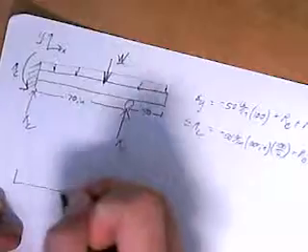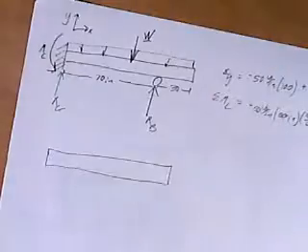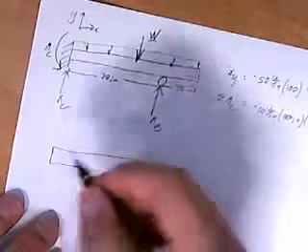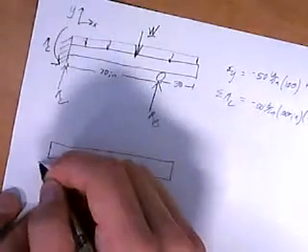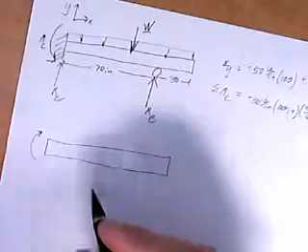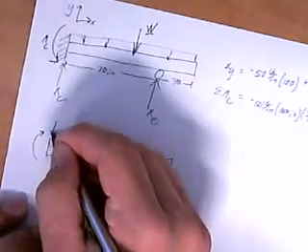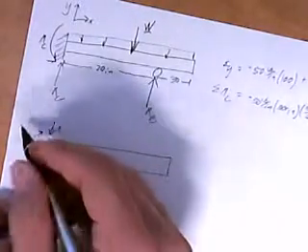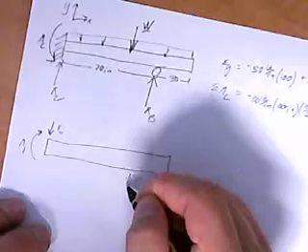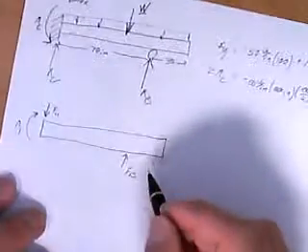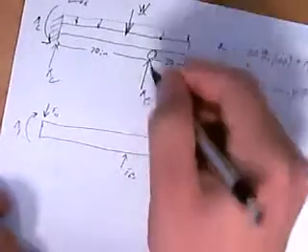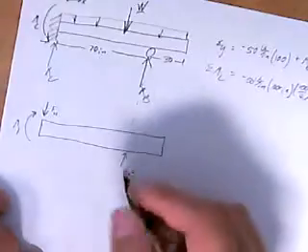So redrawing this free body diagram, if you're looking in the back of your book, we use the Shigley book, Machine Design, Machine Analysis and Design by Shigley. If you look in Appendix 9, you'll see a picture that looks like this, of a cantilevered beam with a force on it. We're going to call this reaction force FC1, and then M1, and then we're going to have FB. I'm using slightly different variable names this time around, just so we can differentiate between this chart and this chart here. But this is all the same. The same distances apply all the way through here.